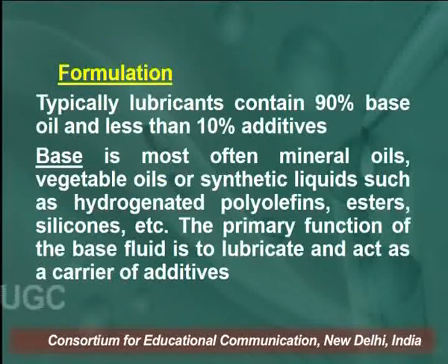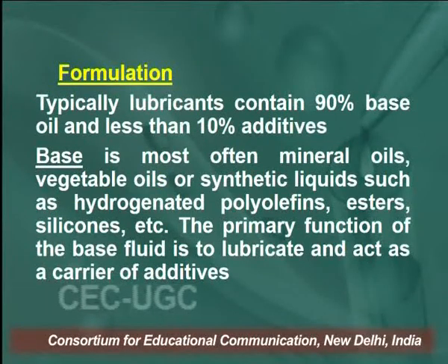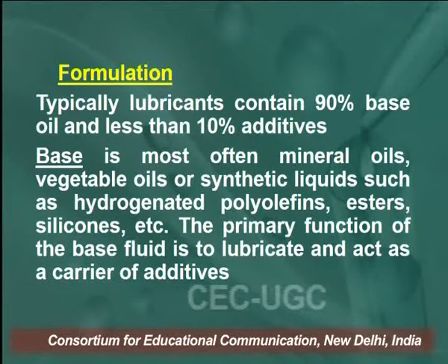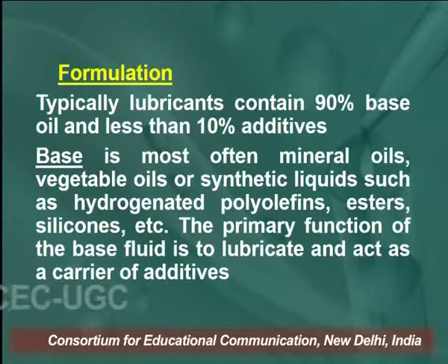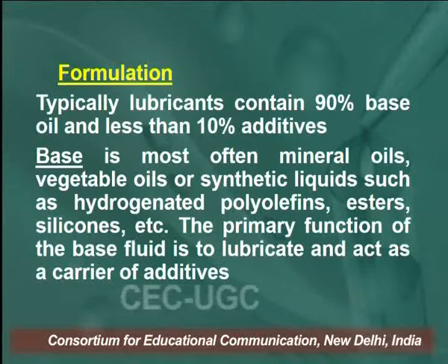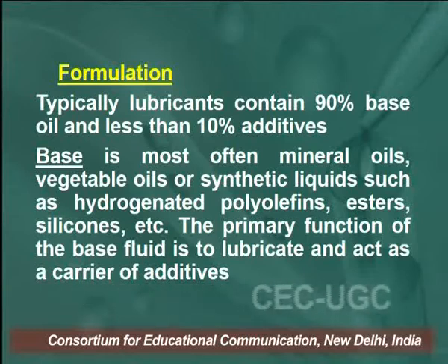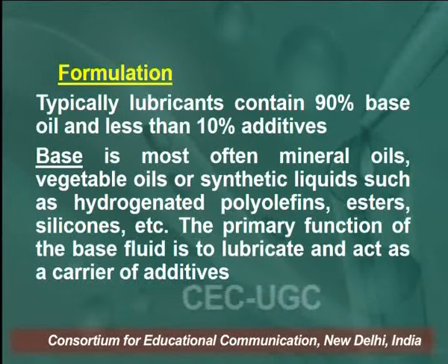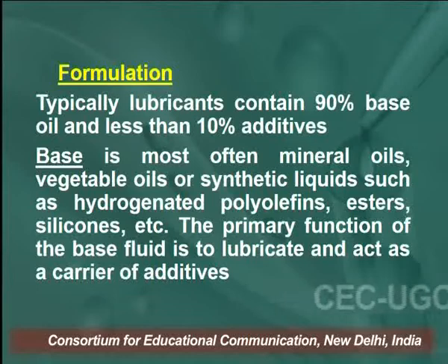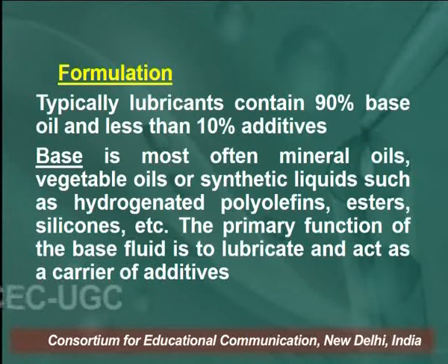Talking of formulation, typically lubricants contain 90% base oil and less than 10% additives. Base oil is most often mineral oils, vegetable oils, or synthetic liquids such as hydrogenated polyolefins, esters, silicones, etc. The primary function of the base fluid is to lubricate and act as a carrier for additives.